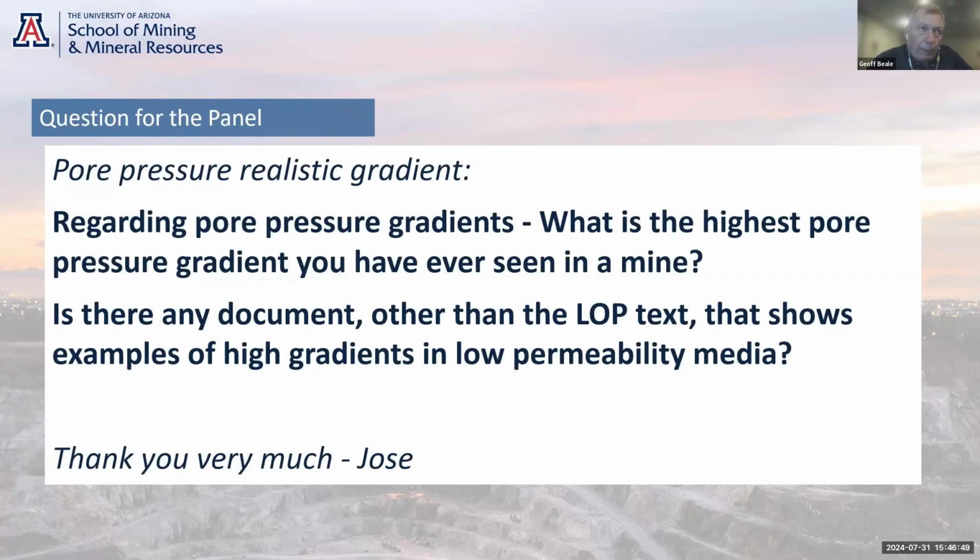The static pressure on that piezometer was 2 meters of head. By the time they constructed a 45-meter high waste dump on top of it, that pressure went from 2 meters to 65 meters, just because of the weight of the waste rock and the compression of the clay.